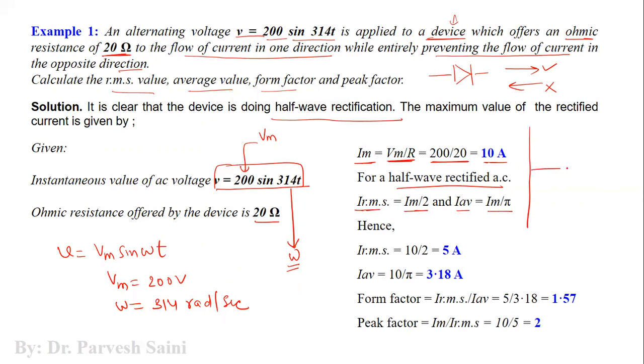If you consider it to be half-wave rectification, it is something like this. From 0 to pi, you have a rectification. From pi to 2 pi, you have 0. And the peak value of this is 10 here, if it is the current i(t). So you can apply the same formula. For half-wave rectification, the time period is this, which is 2 pi.